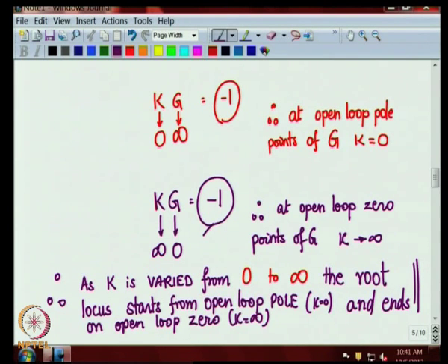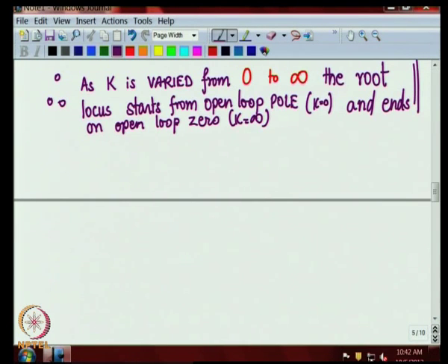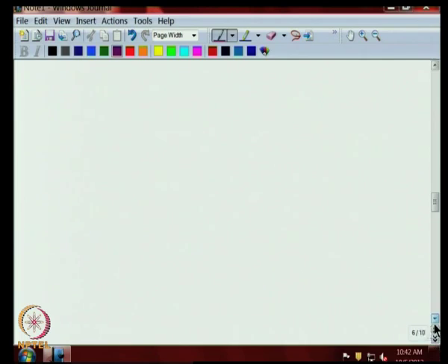Anyway, you need not worry, this is a concept that you should keep in mind when you are trying to place the poles. The computer does the job of calculating all the roots, solving these equations, specifically this equation, and plotting to you the root loci of the system. So, if it is a third order system, then you will have 3 root loci.